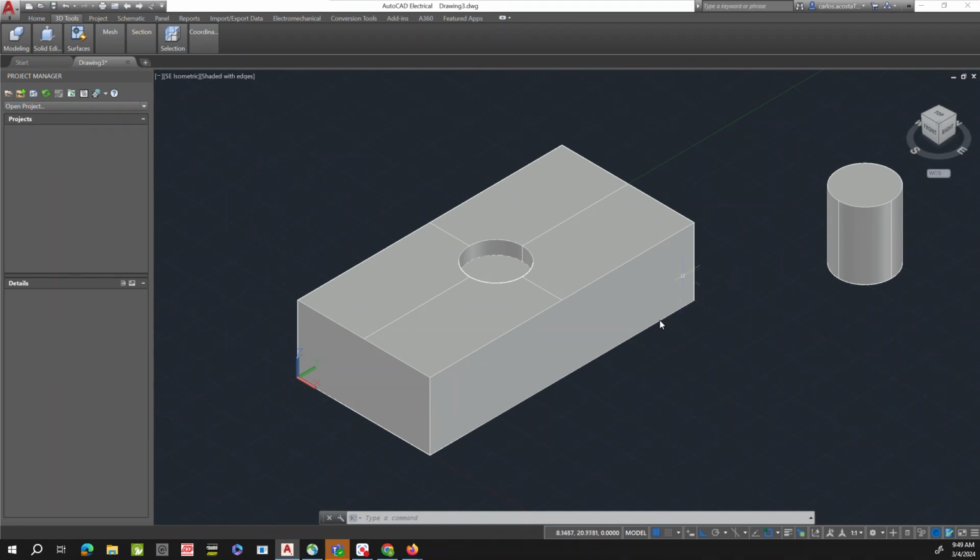So if you want to do the same thing on this face, you simply check the copy edge command and start creating patterns right here. The way we do that, let's do it one more time, is we select this line, enter the base point on that direction, and at 10 units from the reference point.